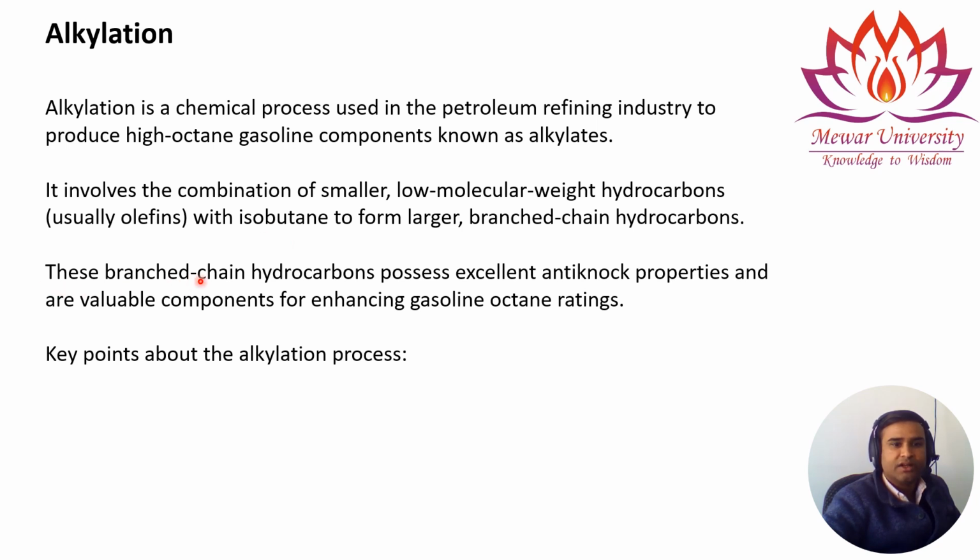These branch chain hydrocarbons possess excellent anti-knocking property. The big branch chain hydrocarbons that come from the alkylation unit, the final product, have excellent anti-knocking property, and are valuable components for enhancing the gasoline octane rating. Once we obtain the high octane number gasoline from the alkylation unit, it has very little knocking in the engine, and the performance of the engine is increased.